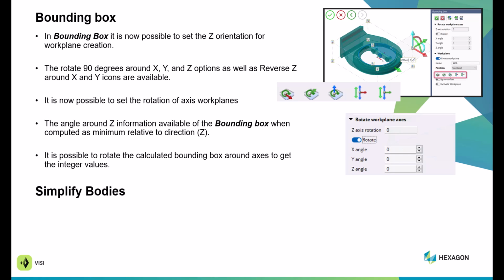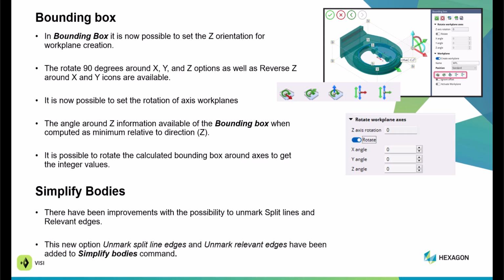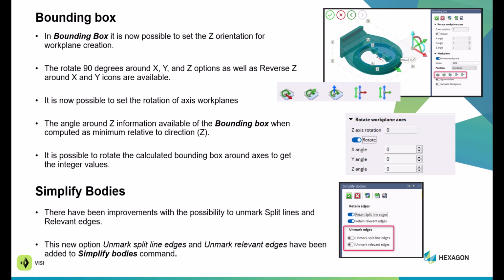Within Simplify Bodies, there have been some improvements, so it is possible to unmark split lines and relevant edges right from the Simplify Bodies command. The new option unmarks the split line and unmark relevant edges within the Simplify Bodies command. You can see the options here.